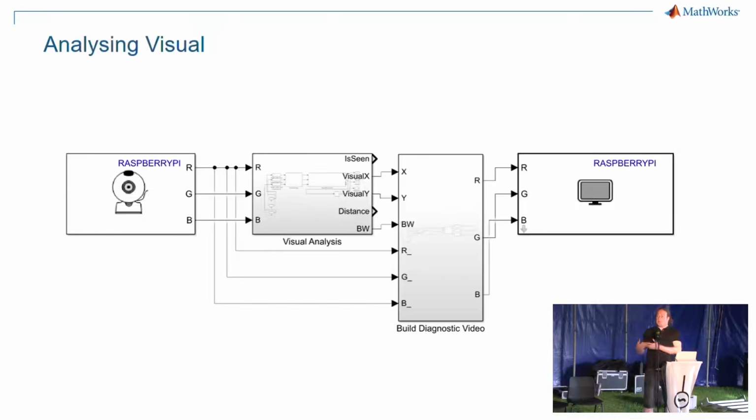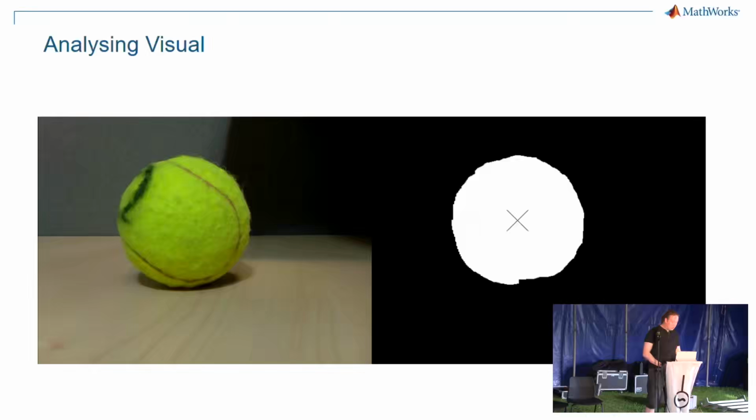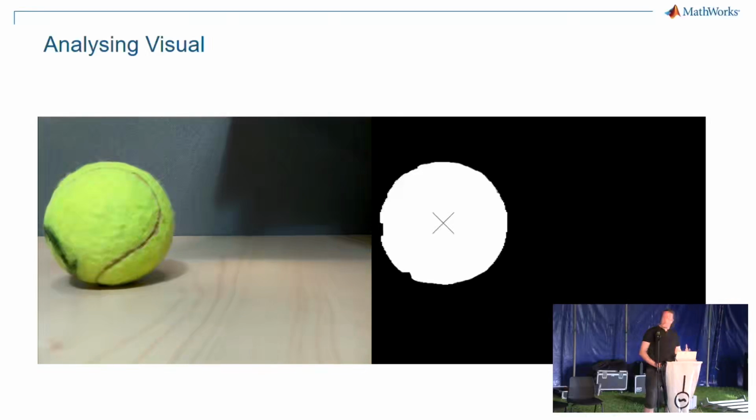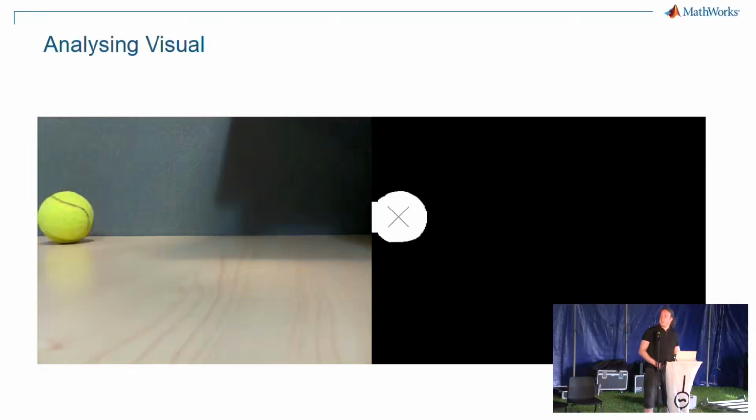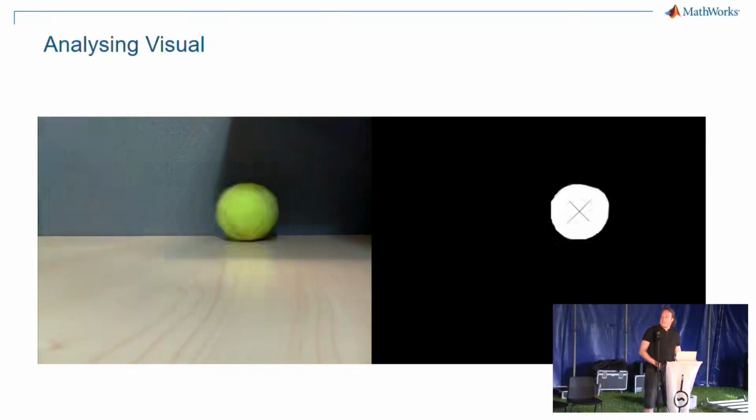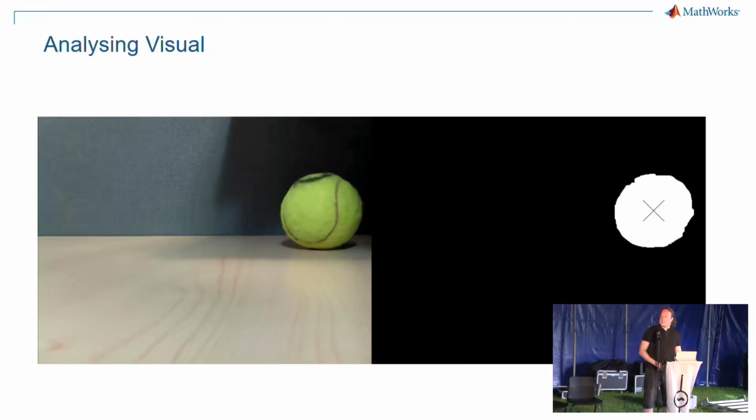So stream the video from the Raspberry Pi to my laptop, say over Wi-Fi, and you get something that looks a bit like this. It sees where the ball is. This is the accumulation of all those four steps, and the Raspberry Pi can see where the tennis ball is. Suppose this is quite well tuned, I've picked the hue values pretty nicely. Let's say I got that wrong and I wanted to play around with it a little bit more.